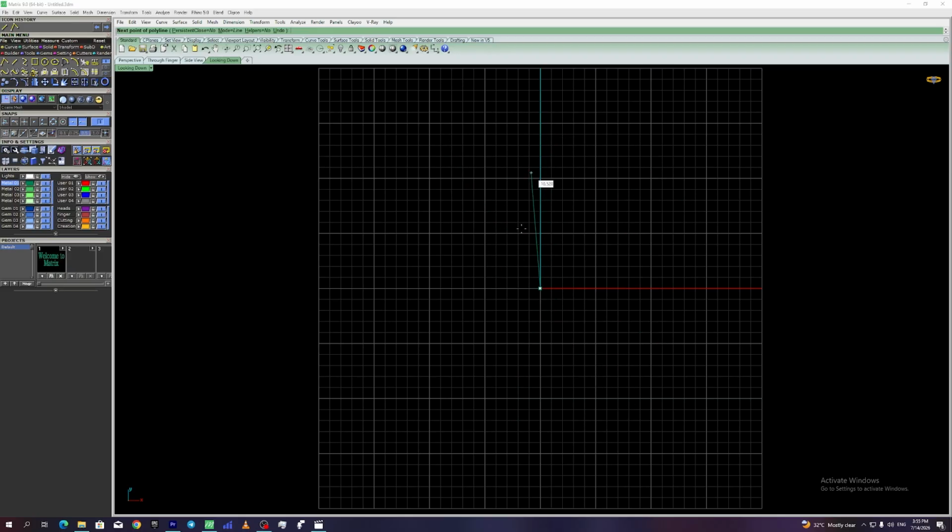And here's something really powerful. After you've started your line, you can type in an exact distance for it. For example, you can say 15 millimeters and press enter. Once you do that, Rhino locks that length, and you can only choose the direction of the line. This is incredibly useful when you need precise measurements, like when you're designing a ring band or a pendant base. So, with this tool, you're not just drawing freely, you're also able to control exact dimensions, which is essential for professional jewelry design.